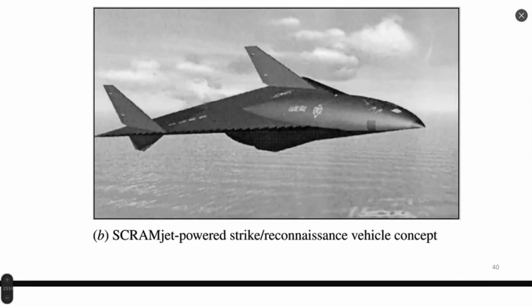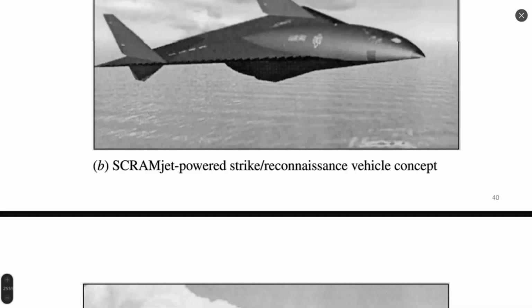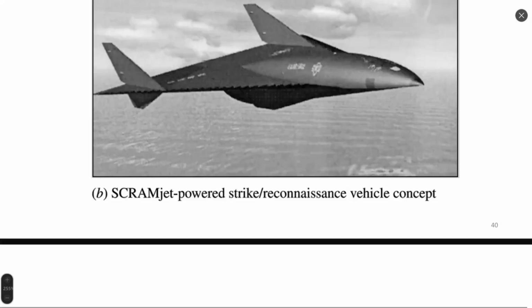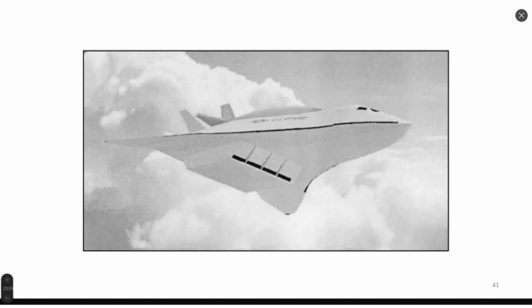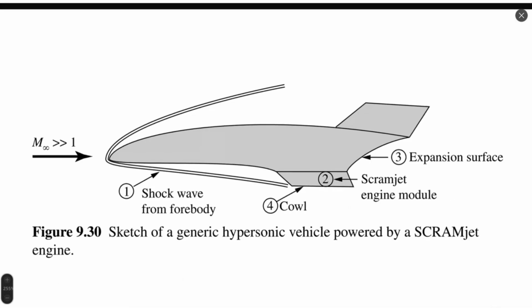There are several examples. Anderson shows some concepts of scramjet powered flight vehicles, just to motivate people. Nowadays there are several examples, and also in Brazil, last year, one of the ramjet or scramjet engines supposed to work in hypersonic conditions was tested. It would be very interesting to investigate what will happen in the future with such a project. The idea of such an engine is based on isentropic compression.